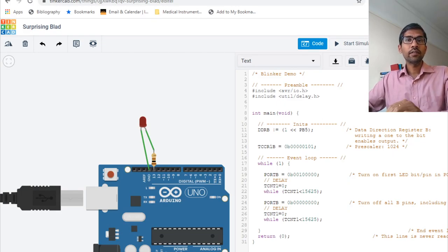Okay, in this video, I just want to look at a programming example to see how timers would work. So here on the screen, you can look at the code, and this is almost exactly the code that we use to blink our LEDs, right? So we have the data direction register, which is setting pin B5 as an output, and then we output a 1 at that pin B5, and then we output a 1.